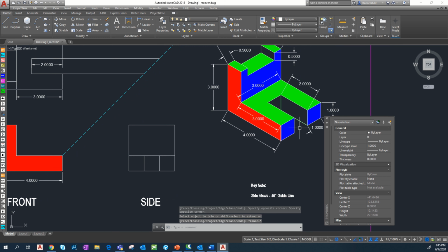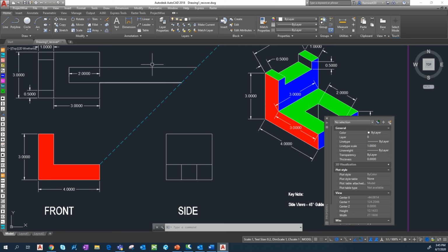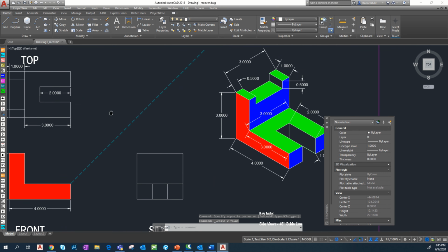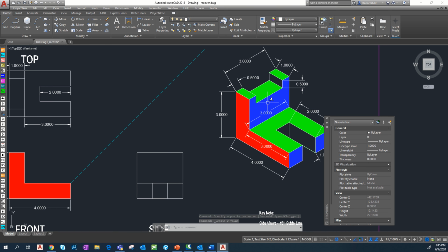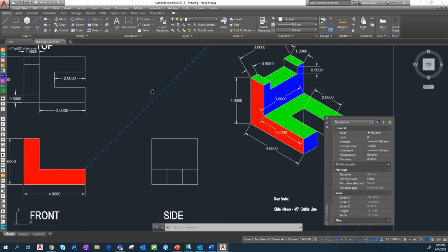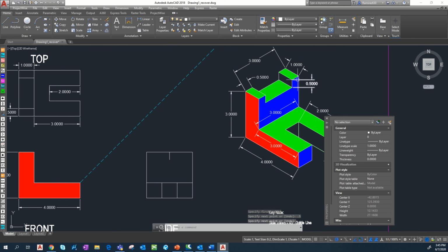So now you have your three. So it's gonna be this one, this one, this one. The reason why it's going straight is because of this line right here, and even in the bottom. So that's how you're gonna see it from the side view. So now we're gonna be drawing this piece right here. So if you guys want to just start from the middle, just go down 0.5. And it's gonna be 0.5 as well for the width.